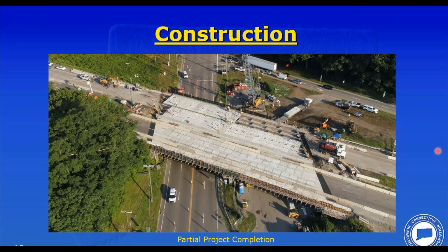Yeah, that's a good point, Tim. And I'd like to bring up the fact I brought this picture back up, and we're not talking much about this today, but we have in the past talked about link slabs. This is an example where precast deck panels are used with link slabs. So at the pier location, which is right here, you see blockouts in the panels, but there are no shear connectors in those blockouts over the link slab region. So this bridge actually has link slabs to eliminate the deck joint at the pier. So it's a little trick we're doing these days in ABC.